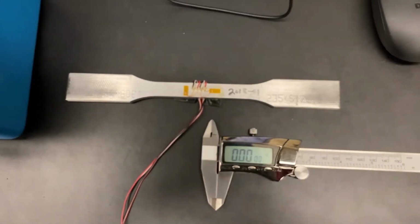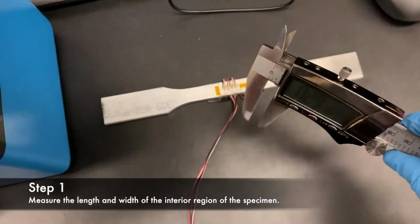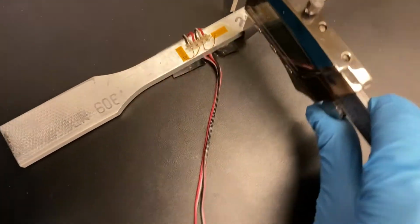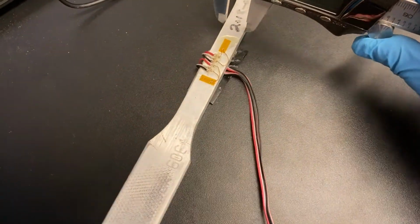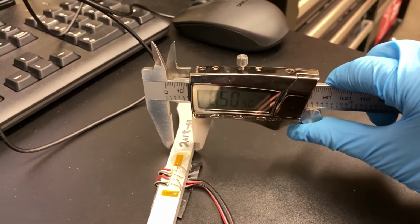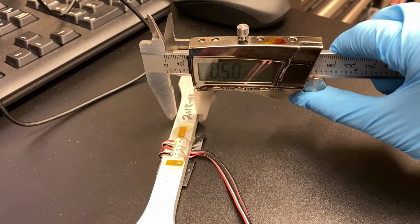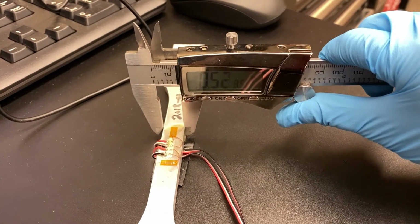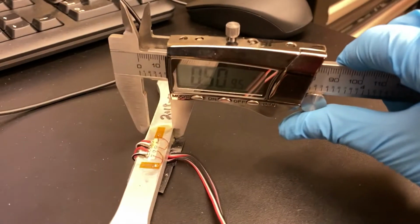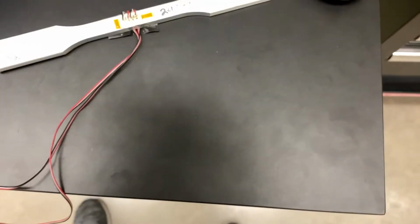This is our aluminum sample of 6061 T6 aluminum. The first thing we're going to do is measure the length and width of the narrower region of this specimen. So our length is approximately 0.505 inches. I'm just measuring in more than one place to get a representation. That location was 0.509 inches.